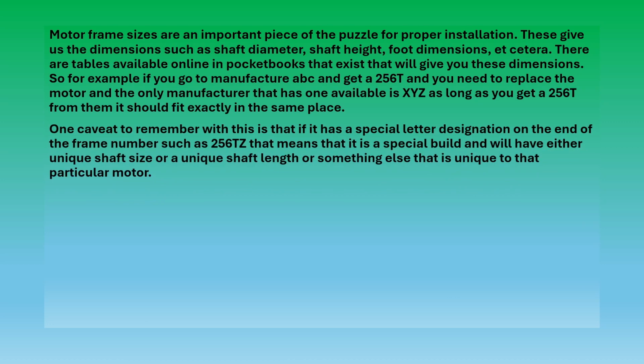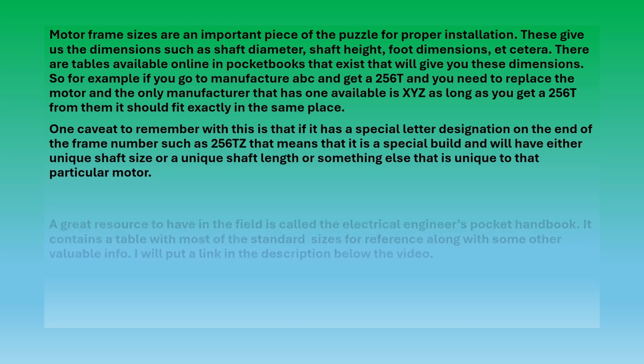One caveat to remember with this is that if it has a special letter designation on the end of the frame number, such as 256TZ, that means that it is a special build and will have either unique shaft size, unique shaft length, or something else that is unique to that particular motor, some sort of unique dimension. And so a 256T may not be a direct replacement. You have to pull up the drawings and see what exactly the Z means. A lot of times it has to do with either shaft diameter or shaft length.